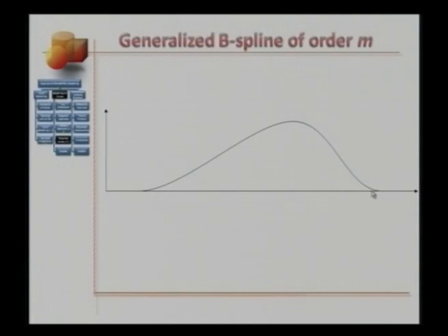Well, as I said, I'll go from right to left. This is my M_m,i(t). Now these two indices have information pertaining to the entire knot span here. This is the parameter axis t. The last knot would correspond to t_i, and the first knot would correspond to t_(i-m).